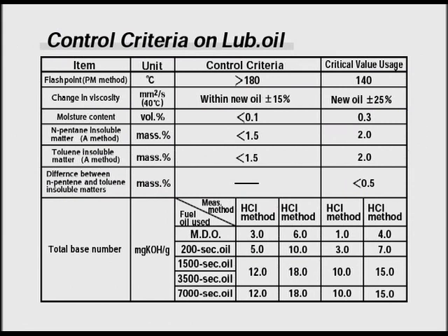Analyze the property of lube oil after every 500 hours of engine operation. Exchange lube oil based on the table.